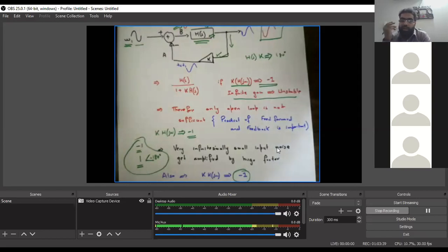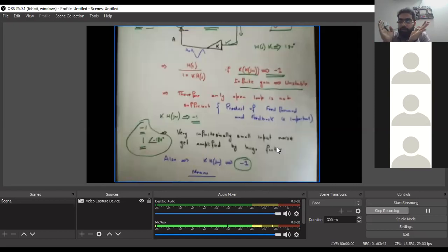When you talk about the magnitude response, the value is an absolute value. There is no sign. All the values are treated as positive. But the phase is going to tell us whether the value is positive or negative. If I have -1 and I need to represent it in polar coordinates, meaning in angle form, the magnitude is going to be 1 and the phase is going to be -180 degrees. And that's what we are depicting from the Bode plot.